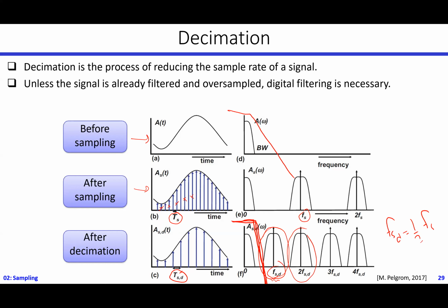So now you can go back to your desired sampling frequency by doing this decimation process, and you have the choice to do an anti-aliasing filter of very sharp response, but this has to be a digital filter, and therefore you can select whatever order you want, so that will be easier for you. Does that make sense to you?